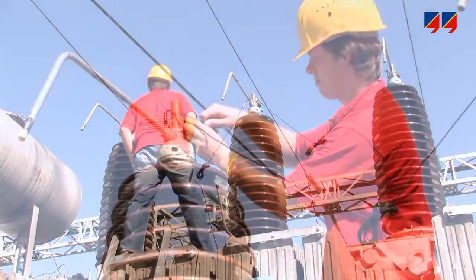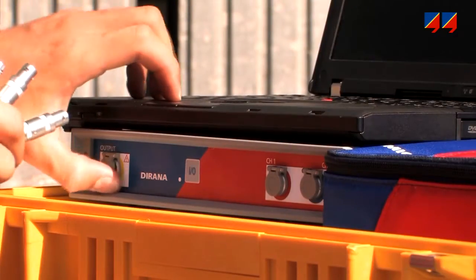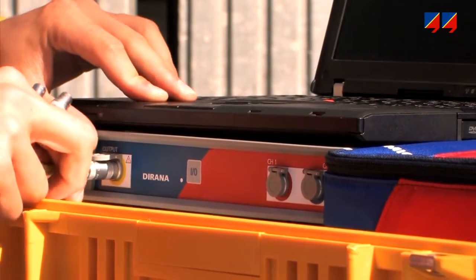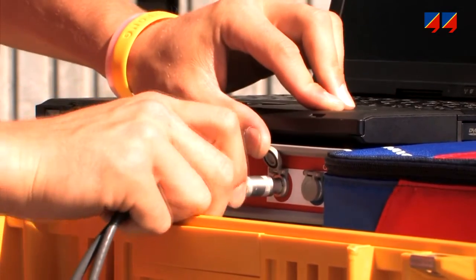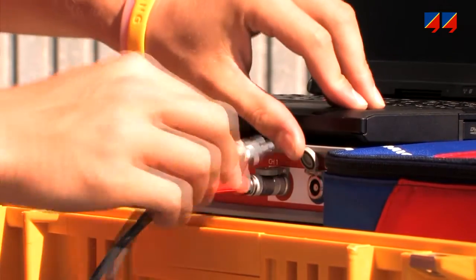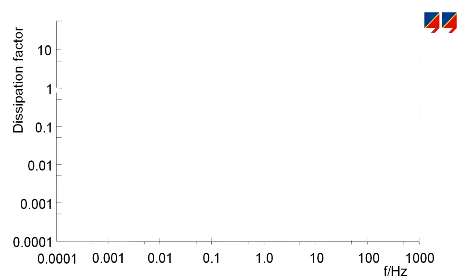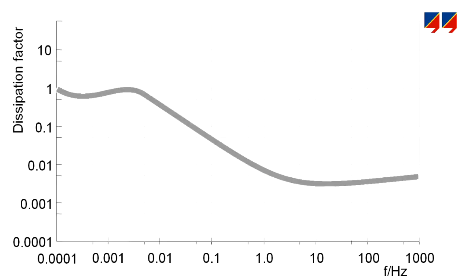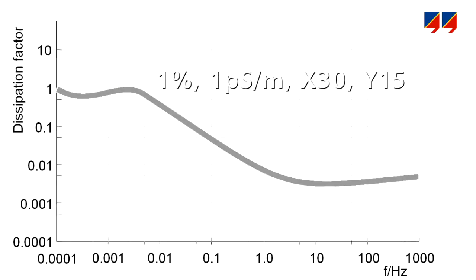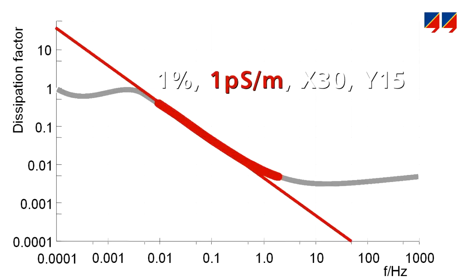Dielectric measurement offers a useful tool, especially for the evaluation of the moisture content, as both conductivity and polarization of dielectrics are values influenced by moisture. During the dielectric measurement, the insulation is exposed to a wide band of frequencies, and its response to these is recorded. These results give a clear picture of the state of the transformer. Displaying the dissipation factor over a wide frequency range uncovers the specific properties of the oil, the insulation geometry, and the solid insulation.